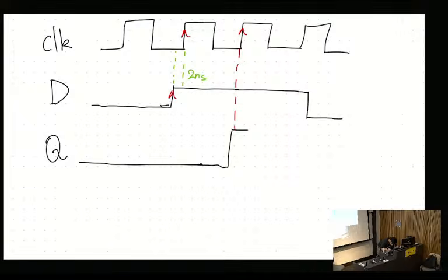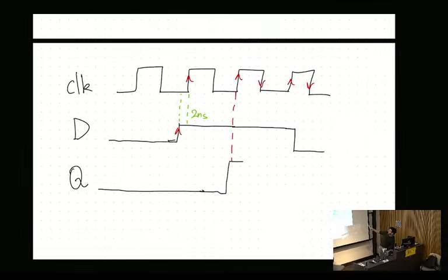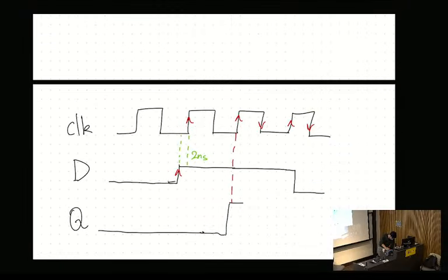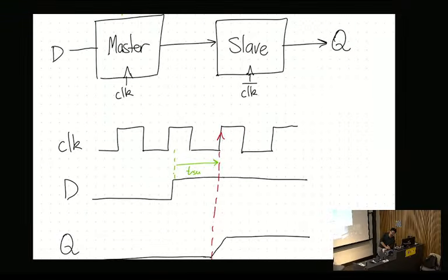Okay, that's good. So just very quickly, both directions are important now. Often we think of a positive edge triggered flip-flop as only the positive edge that we care about. But we can see that they are inverted signals, and inverted for a reason, because on the low clock signal is where the slave actually processes the signal. That's why we use the inverted signal.